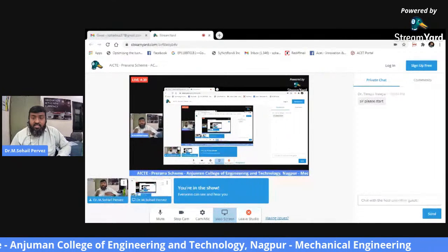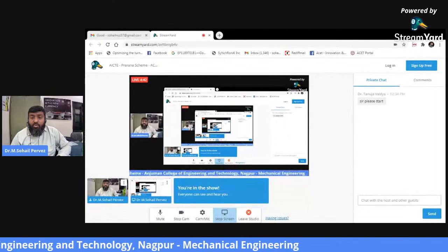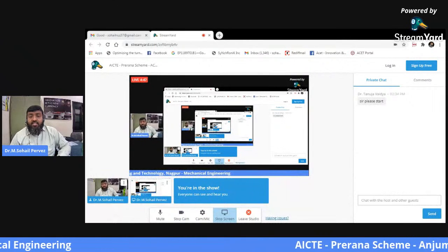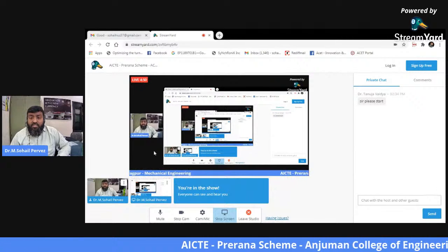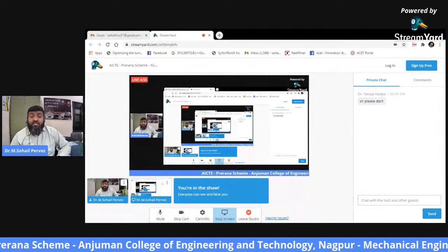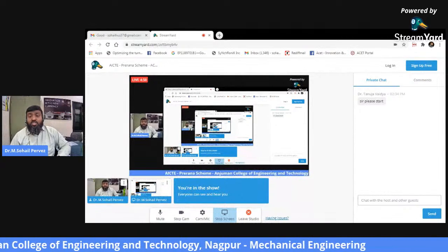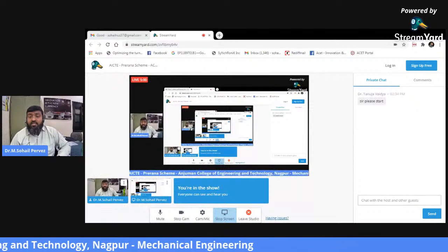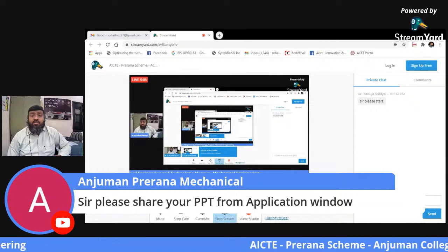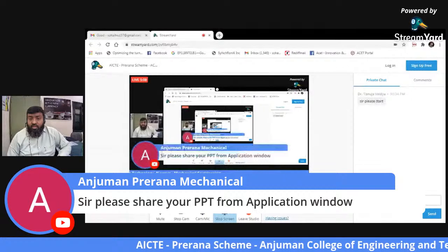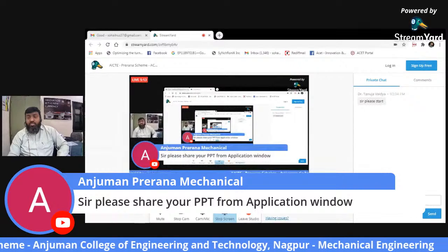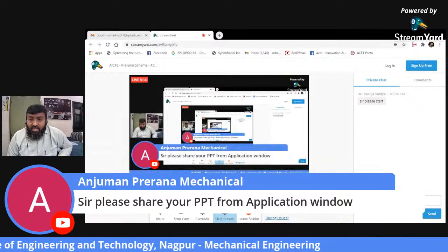So in this case, since the same load is being shared by both the fillets or both the welds, we are adding these, because here the type of joint is single transverse double parallel. That's why we have added these two, and what we'll be getting is either the size of weld or the thickness of the weld, or sometimes it may ask you about the load. So this is the basic idea of how to calculate the dimensions of a weld for different types of welded joints.